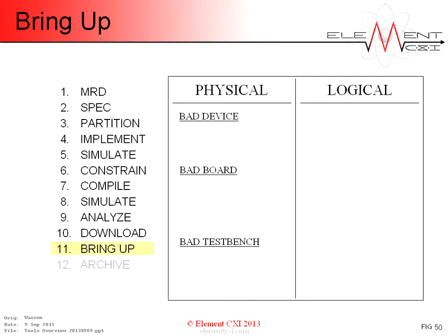The target device might have a die defect, or its I/O could be blown by mishandling, improper operator grounding. The device might succumb to infant mortality. It was good when installed, but dies after a few days or weeks of operation. A board might have some other part bad, or wrong, or missing. Traces might be shorted or open. Layout might introduce noise or crosstalk. Rework might be done incorrectly, or switch and jumper settings might be incorrect.